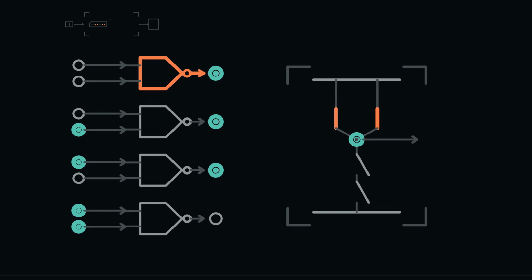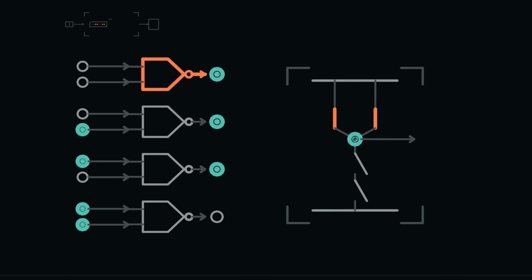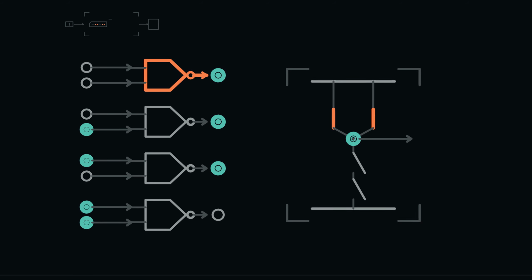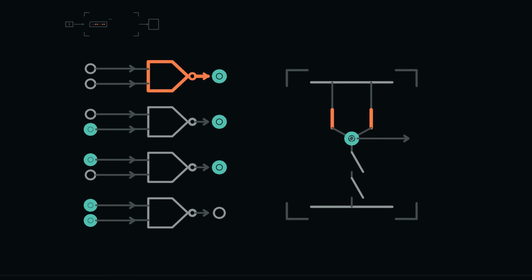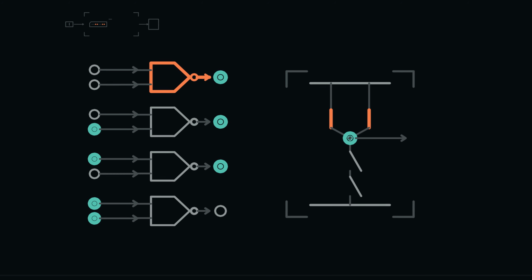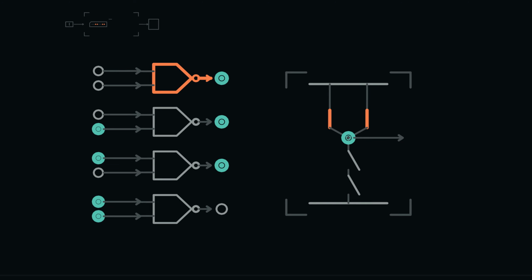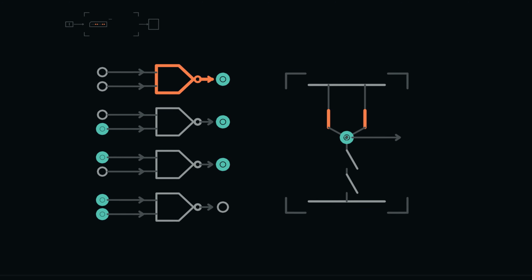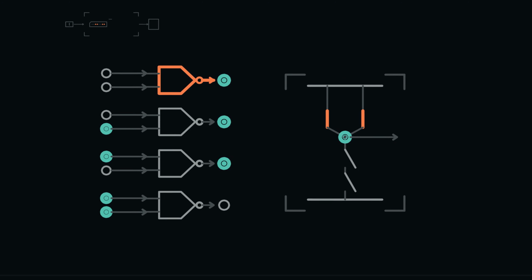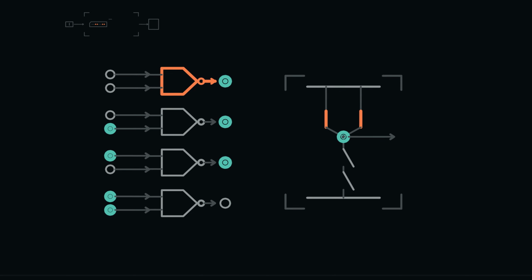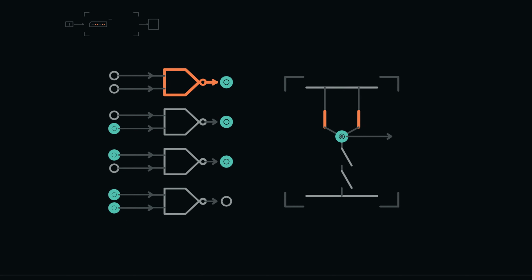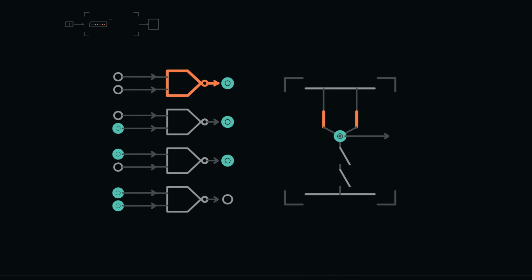Predict the output before the final row is revealed. The left input is 1, and the right input changes from 0 to 1. At first, both are not 1, so the output is 1. After the change, both are 1, so the output becomes 0. Now reverse only the left input. The output must return to 1. If a proposed NAND module remains at 0, that single counterexample is enough to reject it, however correct its other rows may be.